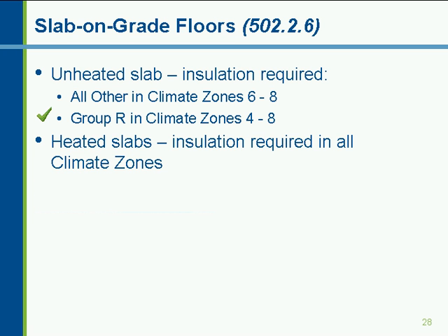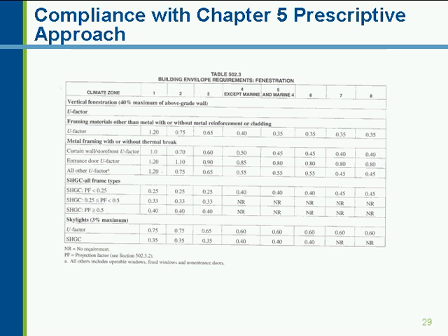And again, that insulation must be placed over the face of the slab. And then you can run it down vertically after that, or horizontal under the slab, or horizontal away from the slab if you wanted to do that. So that's the end of the discussion for the opaque assemblies for R values.